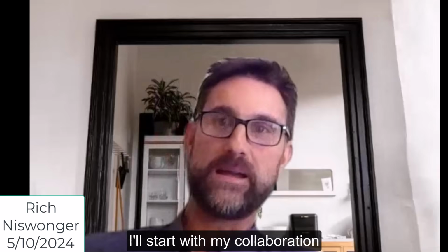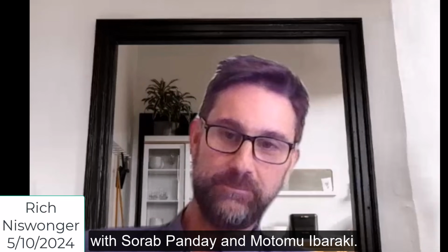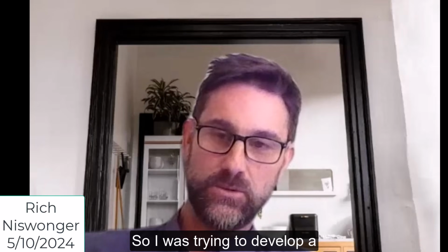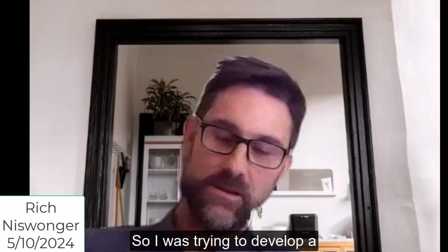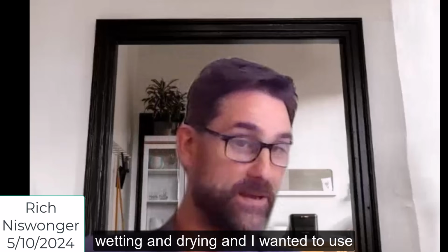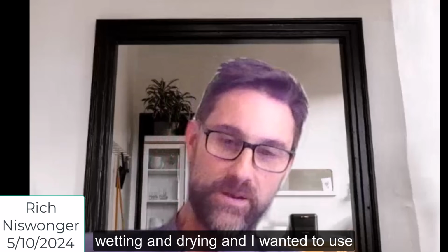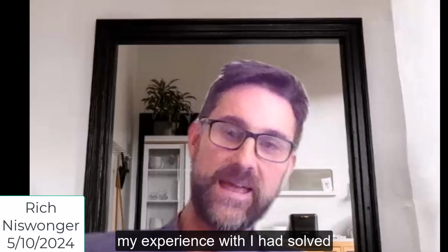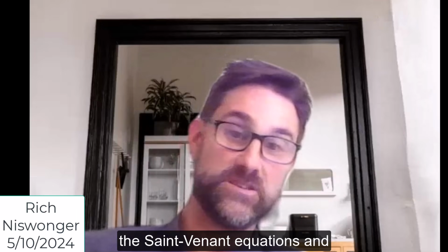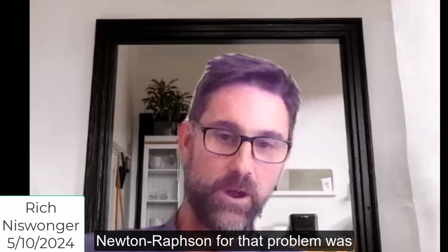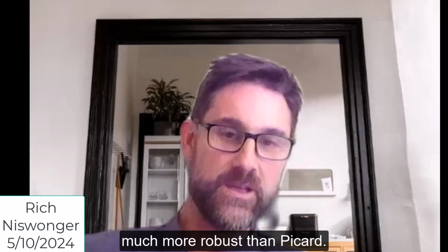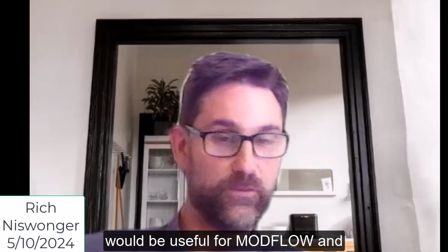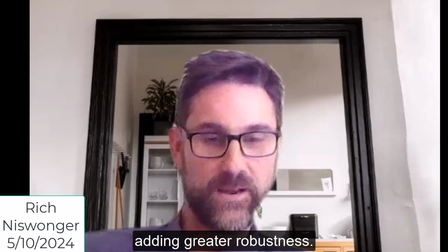I'll start with my collaboration with Sorab Panday and Mutsumu Ibaraki. So I was trying to develop a more robust solution for MODFLOW for wetting and drying. And I wanted to use the Newton-Raphson method because I had solved the Saint-Venant equations, and Newton-Raphson for that problem was much more robust than Picard. So I thought, well, maybe Newton-Raphson would be useful for MODFLOW and add greater robustness.